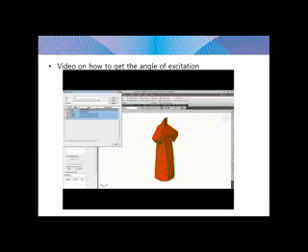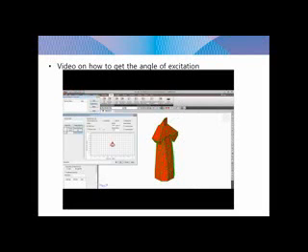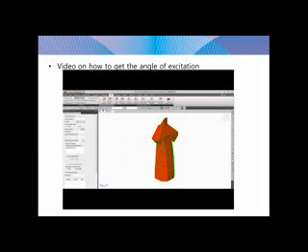And then go into the RS load cases. We have the EQ major. As you can see, there's an auto search angle. Check that, and then check also the major. The scale factor is 1 over 8.5. Then press add. Then same also, just change the earthquake to EQ ortho. Then check the ortho. Then add.